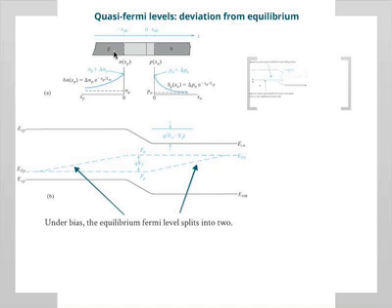Now you see that you can relate these two, they're both exponents. Now this, of course, becomes a quasi-Fermi level, okay? Because they're both exponents, you can equate the two factors on the top, and you can see that of course, the conduction band is basically what it is, right? It doesn't change, except for the bending at the junction, so ignore that.